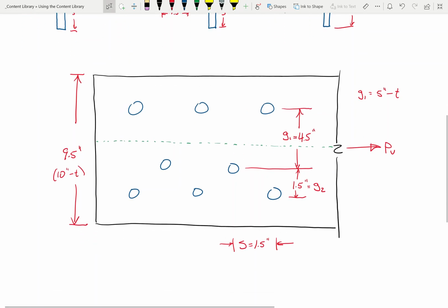Now the other thing I'm going to do is just make sure that we're clear on something. Which is the lead line? Is the lead line these bolts over here, the ones on the left or the ones on the right? The right. Okay. So that means our failure paths are going to go essentially along these bolts here. Now let's make sure that we're clear. Let's put some letters here.